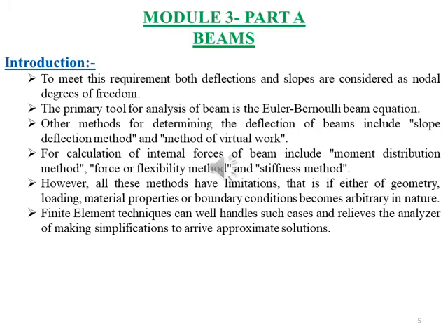The primary tool for analysis of a beam element is the Euler-Bernoulli beam equation. Other methods for determining the deflection of the beam include the slope deflection method, virtual work, and some other methods. For calculation of internal forces of a beam, we have the moment distribution method, force or flexibility method, and stiffness method.